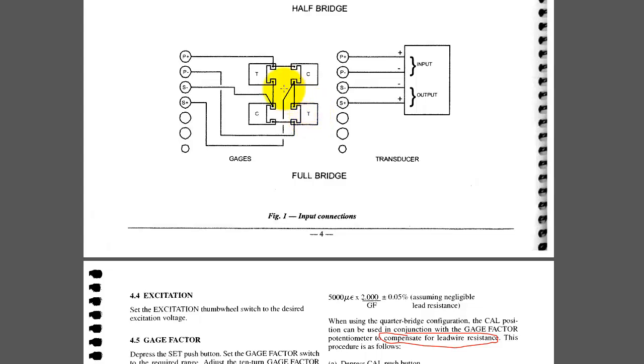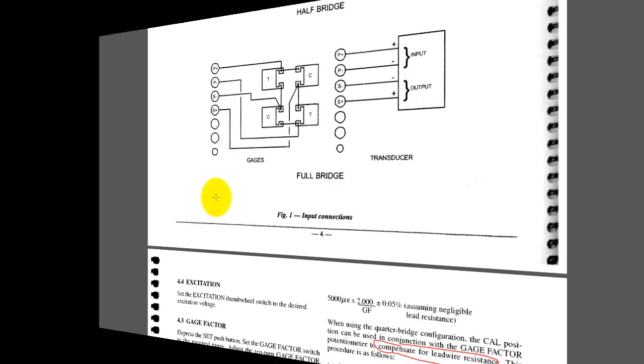So I believe those are T's for tension, C's for compression in aligning the gauges such that they're used on all 4 arms of the Wheatstone bridge. And in this way we can compensate for multiple things. If you're wanting to use these for any of your senior design projects, you should consider, do you need to compensate for anything as an error control? And if you do, maybe consider one of those configurations.